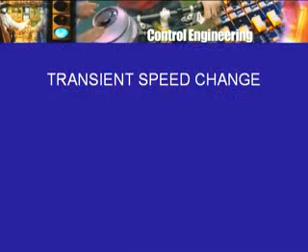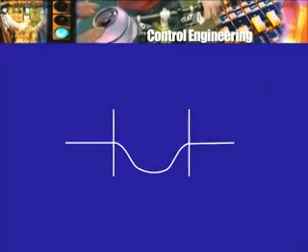It is only in between, during the transient period, that the speed may have dropped. So, if one looks at the variation of speed, it would be omega m, constant till the disturbance, the change in the load torque, took place. The speed therefore dropped, and maybe it remained at a lower value till some time when the adjustment was completed and the speed is back at its old value omega m.